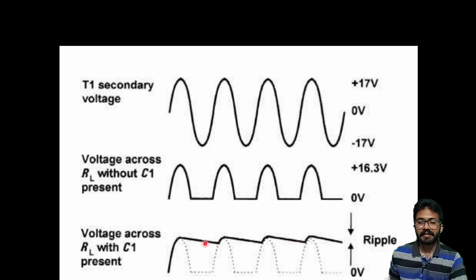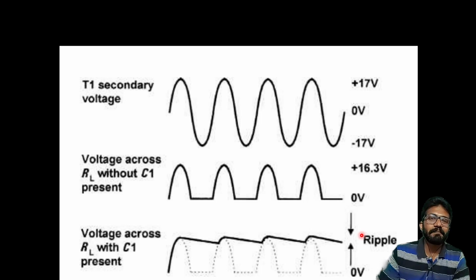That is, in the reverse bias condition, whenever the input reduces below the peak voltage, the capacitor, which is fully charged up to this peak voltage value, starts discharging. Thus, we get a smoothened waveform. And if there is any difference between this point and the peak, we call it ripple. As engineers, it is necessary to maintain this ripple as low as possible.